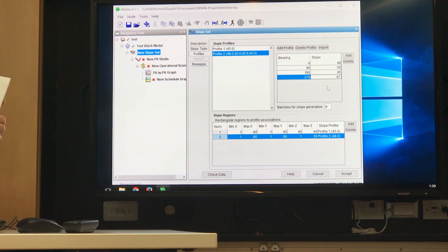So if you have a wall that starts from a point to another point, and you want to assign exactly this specific slope angle, you could say 220 to 220, 48 degrees, 320 also 48 degrees. So basically between 220 to 320 is going to assign exactly the angle that you have entered. Okay, so you could basically fix it for a certain range. Otherwise, it's going to gradually increase in between those numbers.